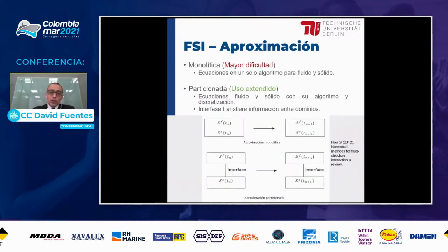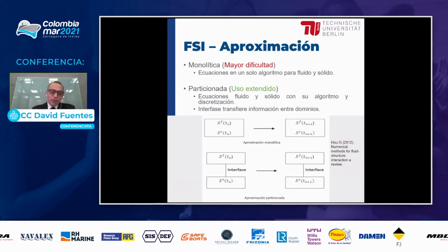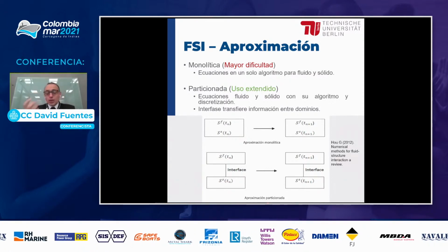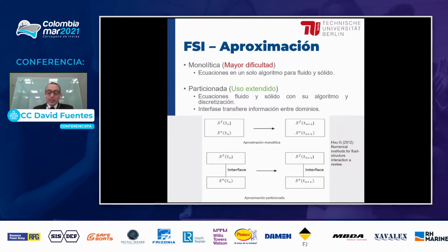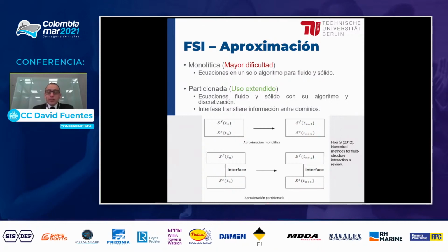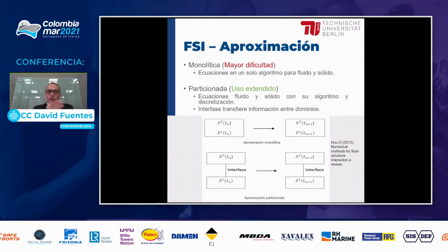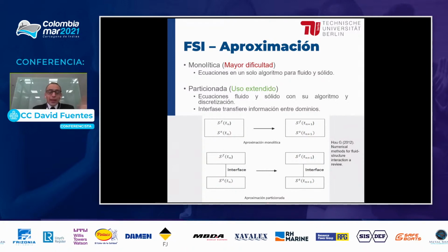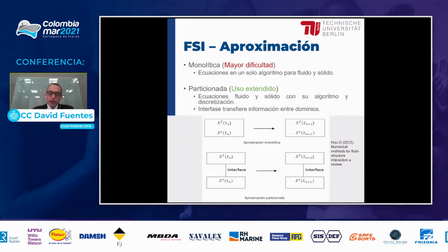Getting more into fluid-structure interactions, we have two main approaches: the monolithic approach, in which the equations of solid and fluid are in the same mathematical framework and solved by the same algorithm. As a positive, the results obtained are more accurate than using the other approach in multi-physics problems.